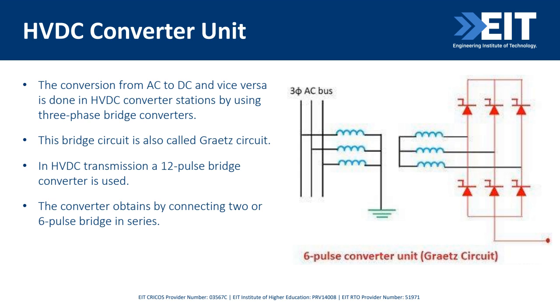It is normally a 12 pulse output because of the positive and negative on each phase. That will produce a 6 pulse output at the DC side, right? So this is called a 12 pulse bridge converter, because we use two of them, 6 in each converter unit.